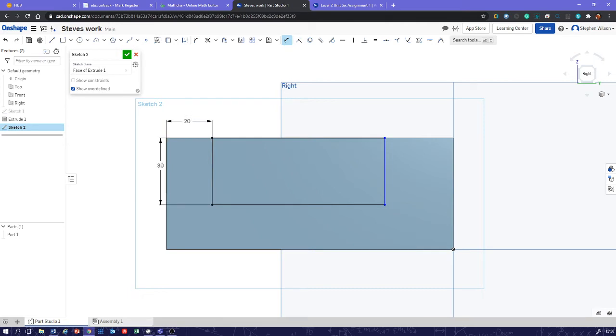So we could either go from there to there at 110 like it is in the drawing, or we could select that line for a dimension at 90. I'll do both of those. I'll start with this one and I'll delete it. So we just click that dimension button.